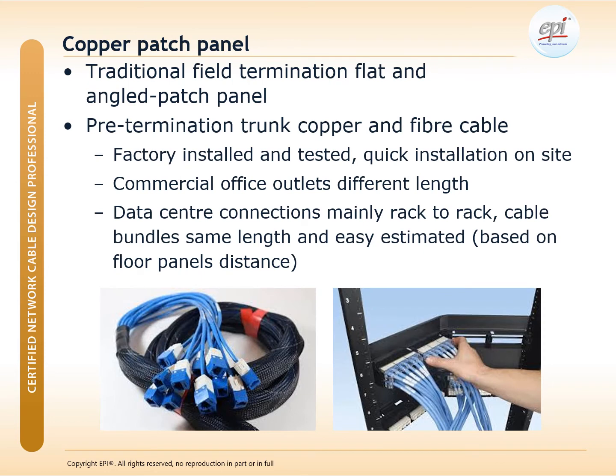Termination of the cables. Now in a commercial environment, the end users are sitting in different desk locations. So that's why all the cables are at different lengths. And the installer needs to install the cables one by one and terminate each cable at the outlet and the patch panel on site one by one.